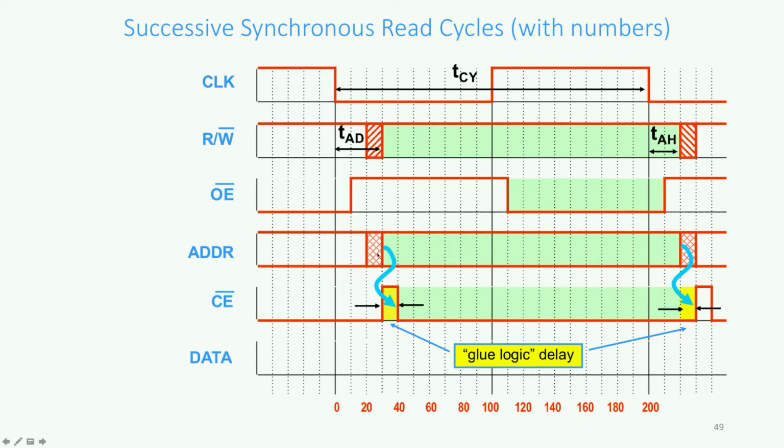The address changed to some indeterminate state, which could flip this to 1. You could consider this a crosshatch as well. In all of our diagrams, we assume that this flips up to 1. And there's actually this 10 nanosecond delay again until we get to the good solid value. So the address changes to the right value here at 30 nanoseconds, and then we've got 10 nanoseconds of delay, and at 40 nanoseconds this chip enable bit is updated to reflect that change.